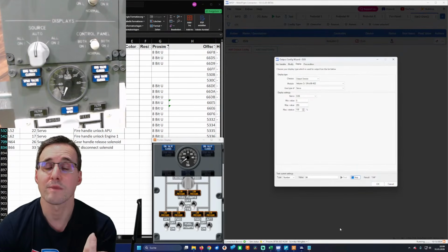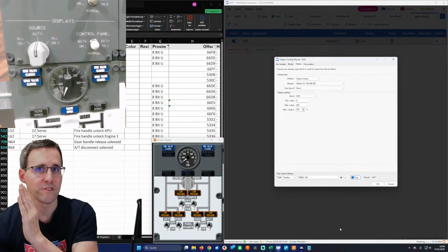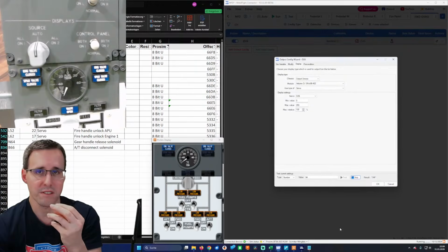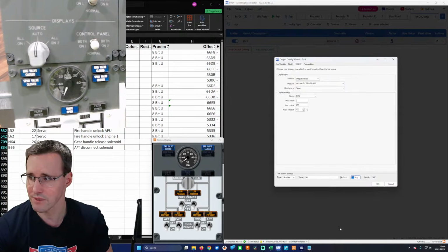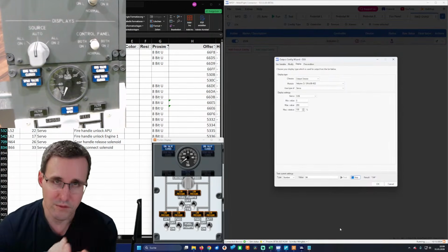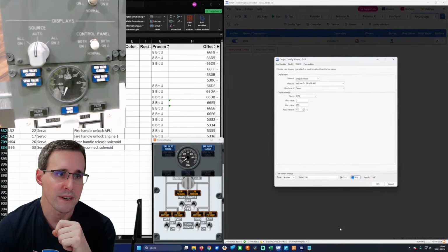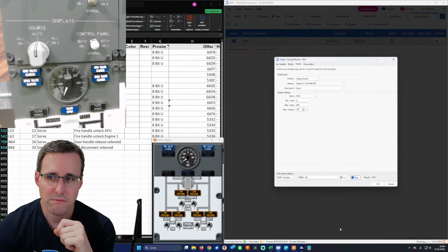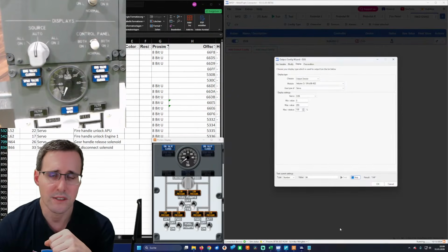For example, when you think of 3D printers, they drive to a 0 point, a homing position, where they touch or come in contact with some kind of switch, and then the stepper motor knows what the 0 position is. Yeah, and these switches I have also implemented into my last gauges. When you have found your way to do it, then you can repeat this.